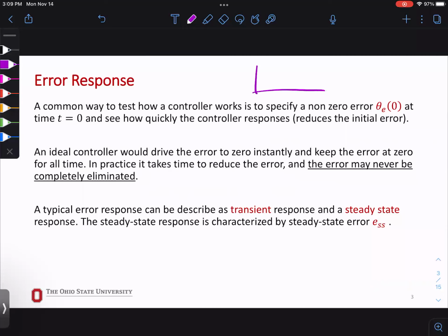So we don't usually see such movements, right? As we talked before, we're going to see this is 0, and then we're going to ramp up to the value. So the purple here is our desired value, let's say theta desired, and the red is how fast our system can get to that. Now, if you remember, I talked about my car, my husband's car, and I think Jess's car. Depending on the motor, how good the car is, we can decrease this time, right? So let's say we call it TS, settling time.